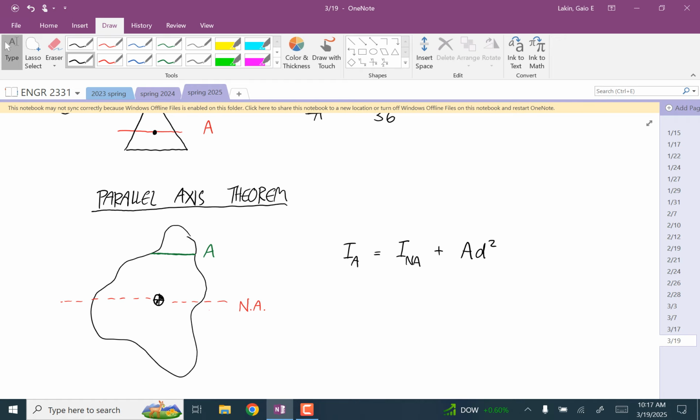It's called the area moment. Yeah, exactly. Does the moment of whatever always have to do with a distribution of something? It always has to do with a distance. The first moment is just the thing times the distance, and the second moment is the thing times the distance squared. And so these are both second moments of some property. Of some property, correct.